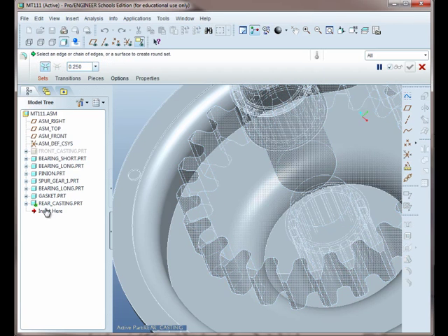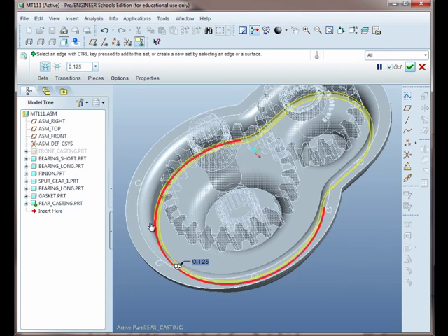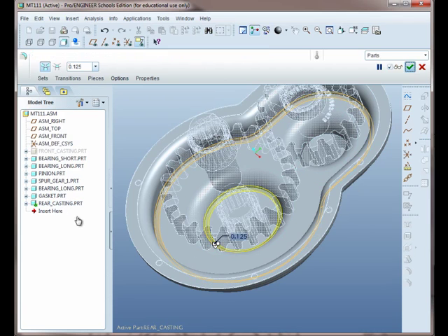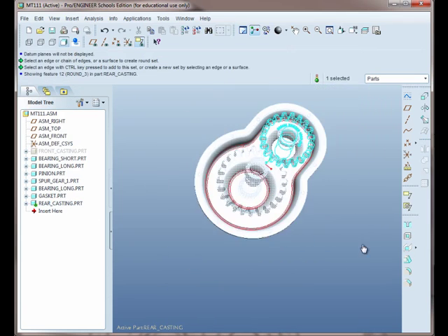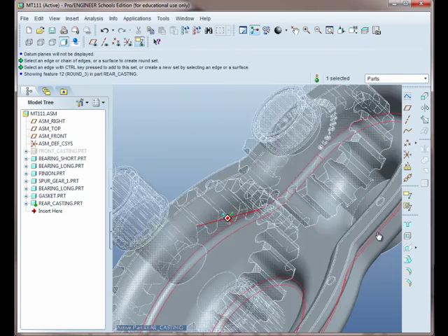and we'll just make 0.125 our default on the inner edge here. Also, you could select that edge there and leave the other one alone on the other side. We do need to cut out this hole here though.